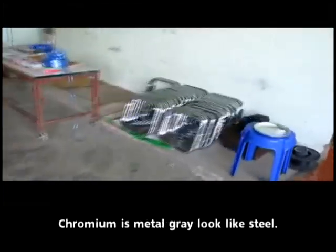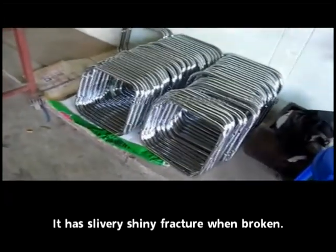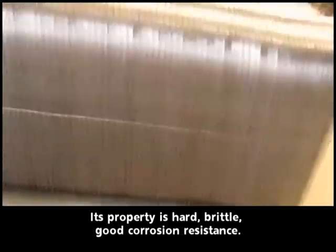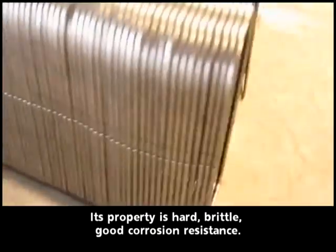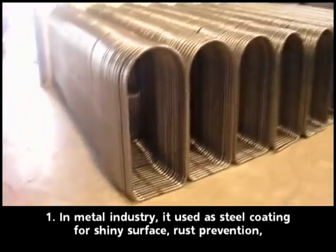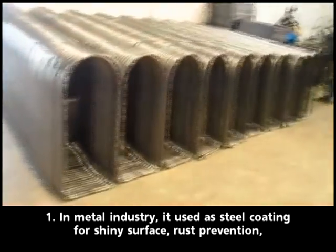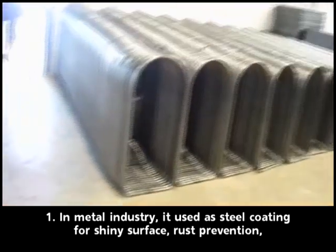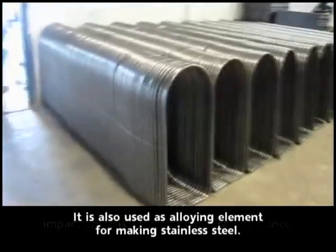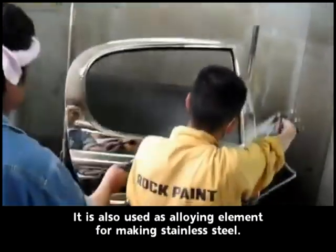Chromium. Chromium is a gray metal, looks like steel. It has a silvery shiny fracture when broken. Its properties are hard, brittle, with good corrosion resistance. Application of chromium. 1. In the metal industry, it is used as steel coating for shiny surface, rust prevention, impact resistance, and chemical resistance. It is also used as an alloying element for making stainless steel.